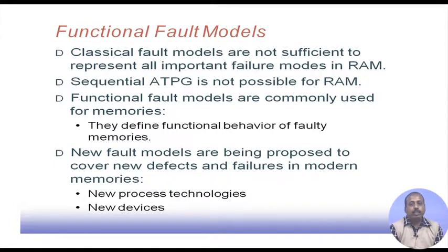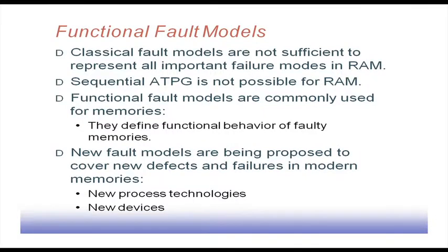So, faulty memory, like two cells getting the same value, coupled to each other, or some cell reaching and continually holding a particular logic level. So, some sort of stuck-at fault will be there, but there are some other types of coupling faults that will come into the picture. So, we will see them.